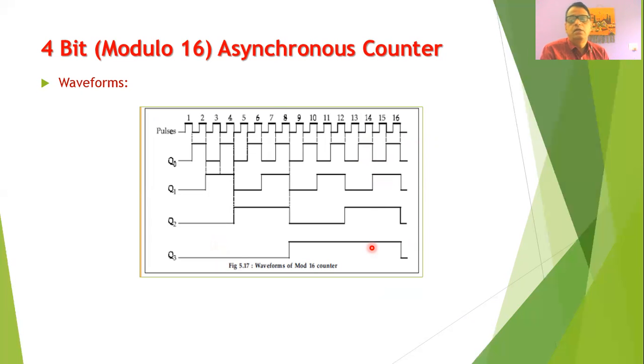So friends, it is possible to construct an odd counter also. For example, if you want to construct a mod 10 counter, you will also require 4 flip-flops, because by using 3 flip-flops you can count only 8 clock pulses. And you need to make an arrangement in the circuit.